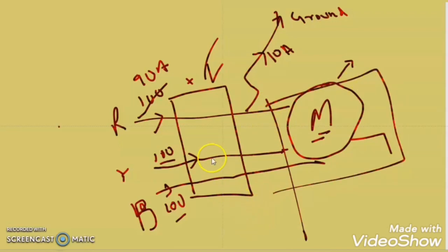But this tripping of the circuit breaker through ELR is not to protect the motor. It is always to protect the human, as this 10 ampere of current may cause death to the human. So ELR will trip in order to stop this 10 ampere of current which is flowing to the ground. Hope you understood the main purpose of ELR, and of course while complying with the main purpose of ELR, that is to protect the human, it is giving a byproduct which is also good for the equipment.